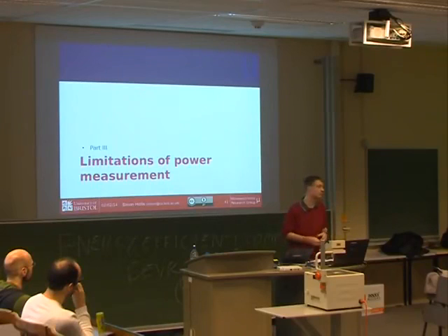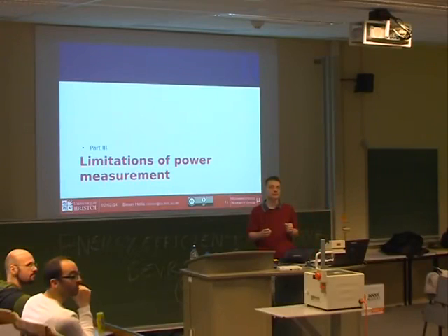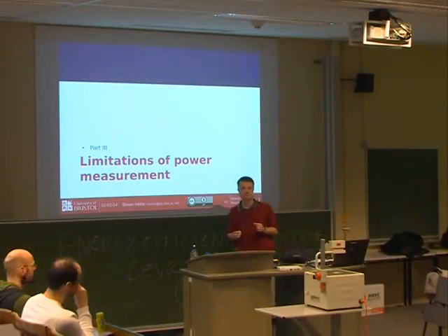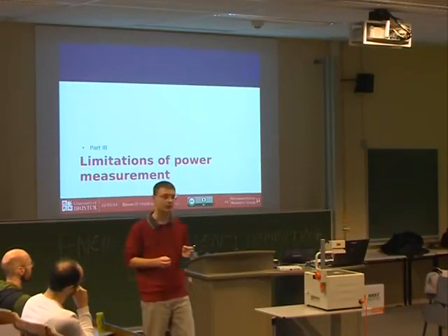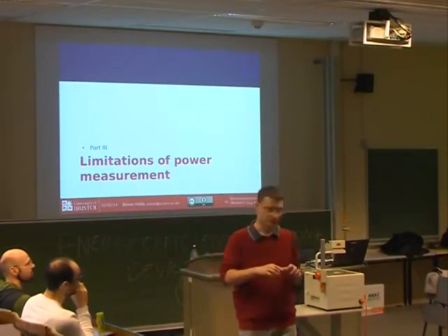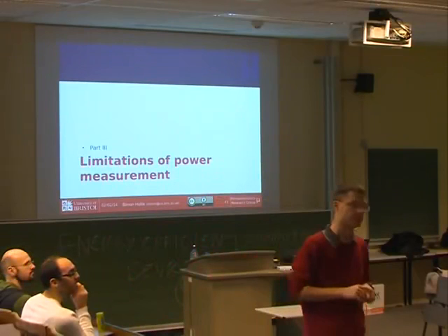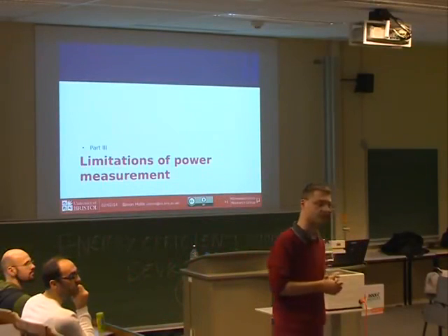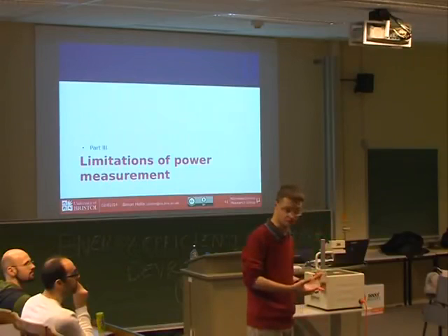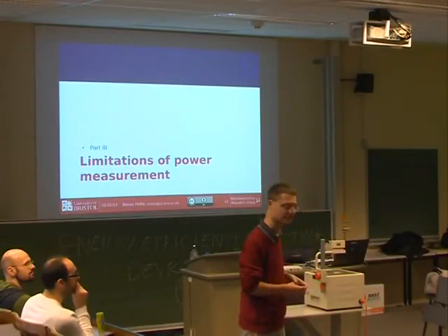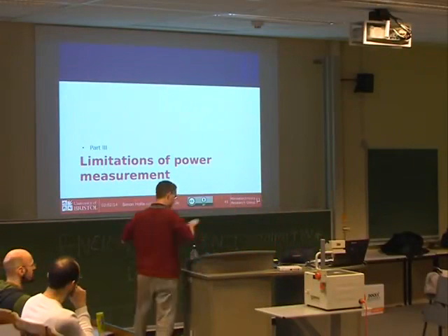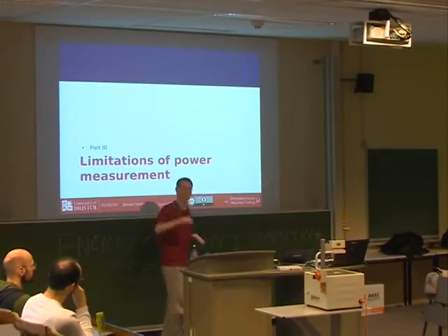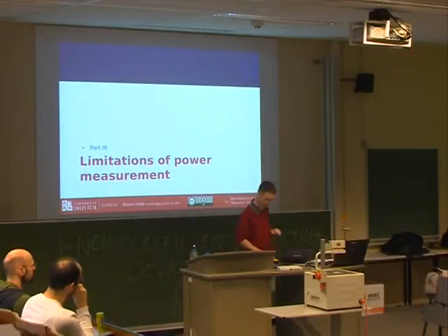So the shunt resistance is something we control. What about non-linearity of the ADC? Do you take that into account as well? That will be specified in the data sheet. Typically, ADCs are internally calibrated to produce a linear output in the binary representation, but these things depend on the ADC that you use, and you have to read the data sheet. It's always a caveat. So you normally get a linear binary representation, even if the ADC itself is not linear.